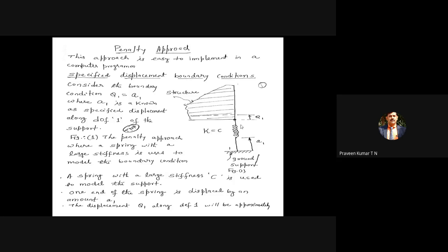Depending on the stiffness value, we can get a 10 mm deformation for the same end of the fan, the upper end of the fan rod, or we may get very, very low displacement, or sometimes zero displacement. Everything depends upon the stiffness with which your fan is coupled to the roof. In general, it is referred to as mounting, how it is fixed to the roof. That is what we do physically or mechanically, but your finite element package will understand only in terms of stiffness. You have to express it in terms of stiffness.